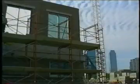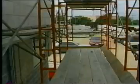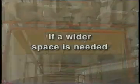The second way to prevent planks from slipping or giving way is to make sure that each platform on all working levels is fully planked or decked between the front uprights and guardrail supports. The space between adjacent planks and between the platform and the upright should be less than 1 inch. If a wider space is needed, for example to fit around uprights when side brackets are used to extend the platform's width, the opening shall never exceed 9 1/2 inches.